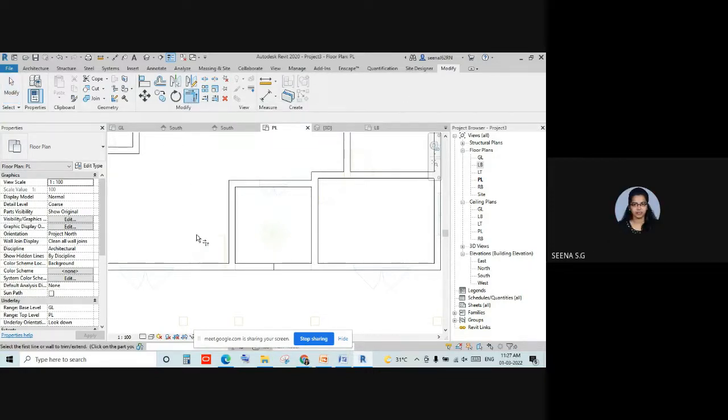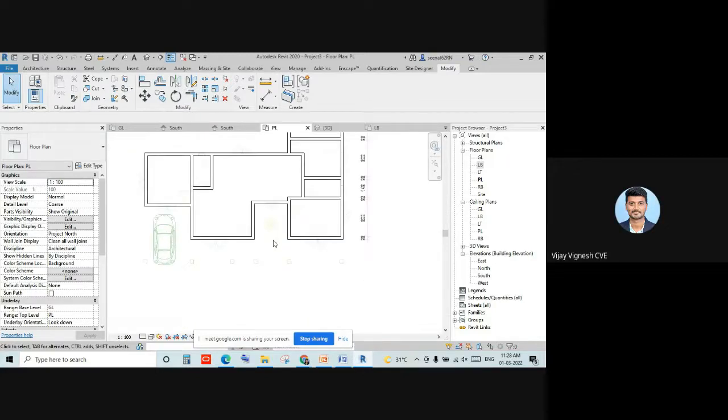Then select two walls that you want to retain in your model. So I want to retain this area and this area, right? I want to trim this projected one. So by using this tool, first select what you want to retain in your project area. So this is the area I want to retain, and again this one. The opposite one is removed. I want to retain this wall and this area also. So this is the way to trim.